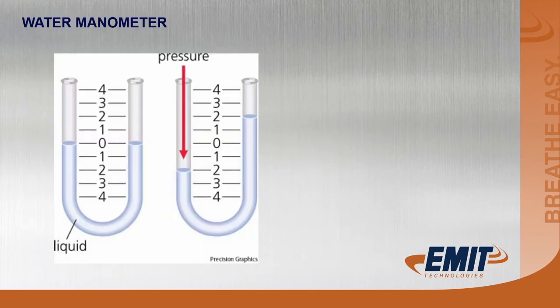Okay, what is inches of water column? Well, we use a water manometer. This would be a true water manometer here. And once we push down by 2 inches, that means we've got 4 inches of differential here. This one is showing 4 inches of water column. It's not very much pressure. 5 inches is typically max for most naturally aspirated engines.